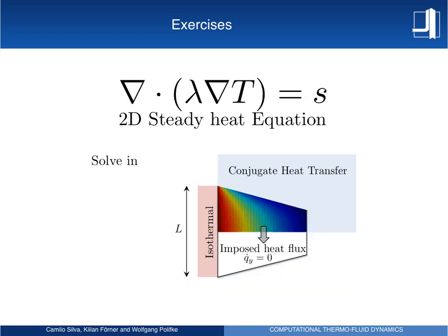And once you discretize, this is how it should look. So you have some temperature distribution, from hot to cold. Then you can imagine these as iso lines of temperature that will be perpendicular to this surface here, because you are imposing a heat flux equal to 0. So this is something we will discuss, but you have to already be aware of how to evaluate the correctness of the results.